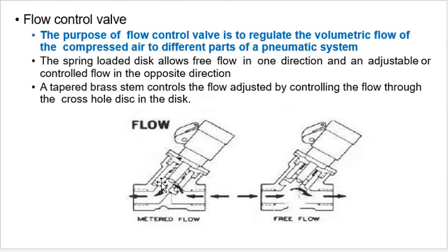The tapered brass stem controls the flow, adjustable by controlling the flow through the cross hole in the disc. Here the metered flow is there, here the free flow is there.